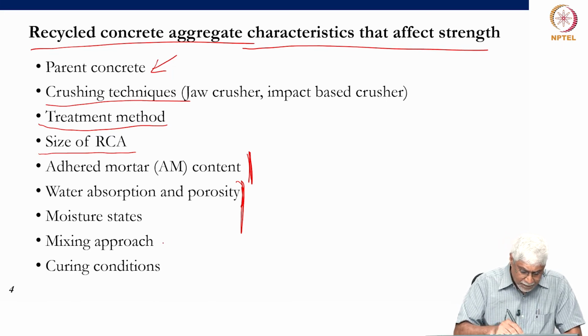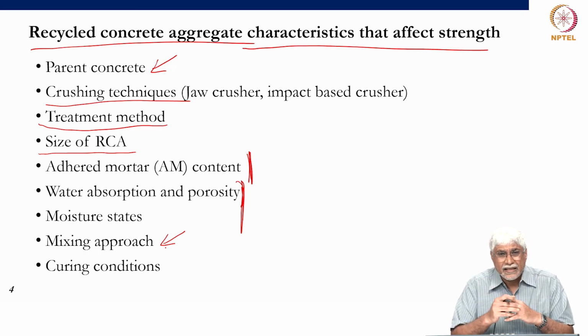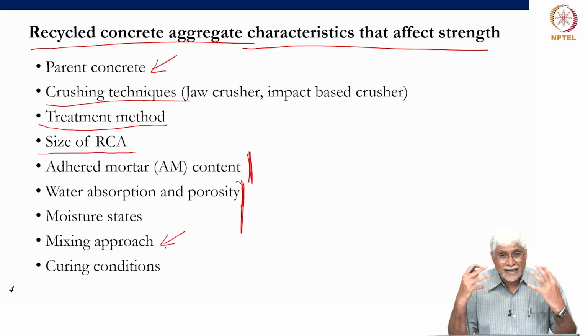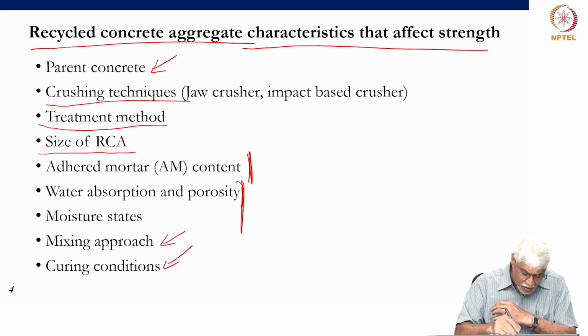The mixing, because we want to be able to saturate the adhered mortar, the surface of the new aggregate, meaning the recycled concrete aggregate should be saturated, should be coated with cement paste. So, we want the mixing to be proper. We will see later how two-stage mixing, where a little bit of saturation time is given to the aggregates, comes out much better. And curing conditions always.